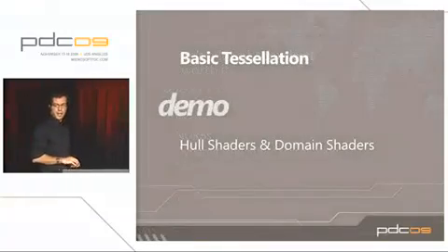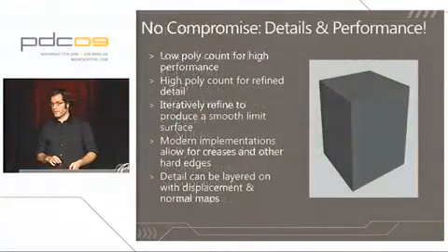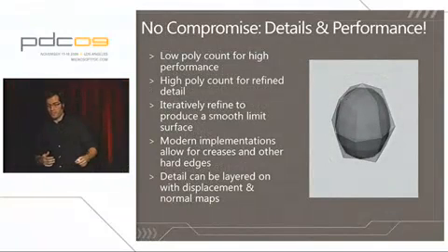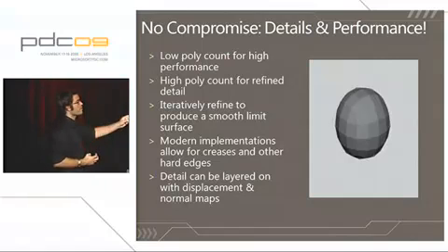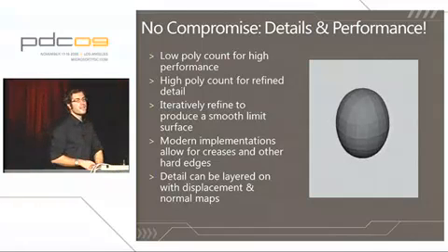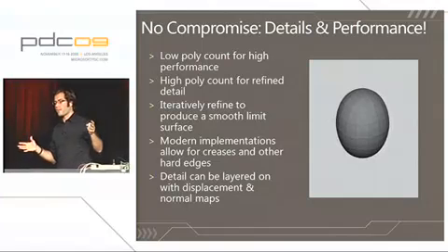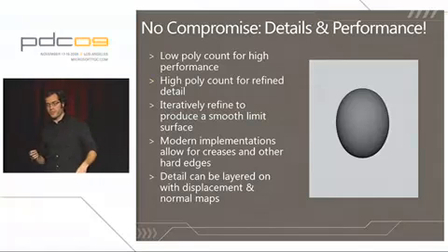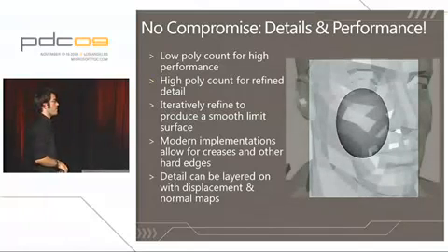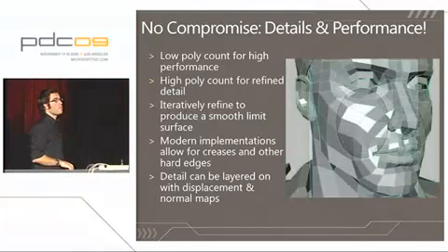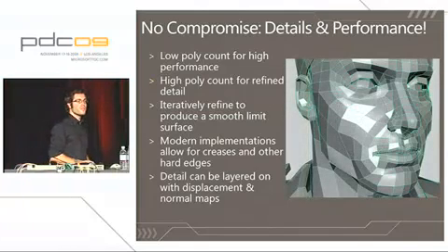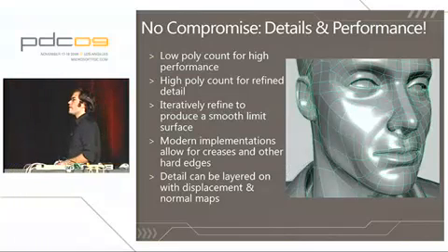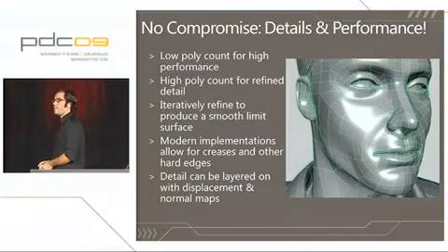The last thing I want to talk about, I went backwards instead of forward, sorry about that, is this idea of subdivision surfaces. And you can actually see surfaces walking through a subdivision algorithm here. Essentially what this does is double the complexity, so make double the number of triangles, and then do some smoothing over those to make it an even more smooth surface. This is called Catmull-Clark subdivision. It's used very widely in the movie industry. So pretty much any movie you see with CG, they use Catmull-Clark subdivision surfaces to create their models. This was innovated at Pixar, and there are a lot of assets available in this.